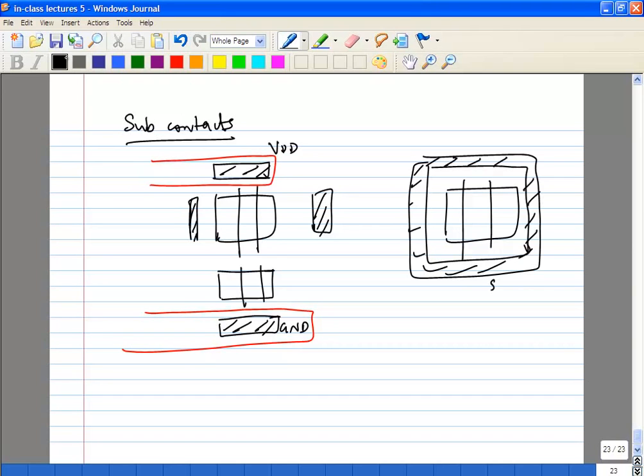So that's as far as your substrate contacts go. So what does the substrate contact do? If you have a switching transistor, say an inverter given a clock signal, the substrate will always have some impedance, some inductance or whatever. So definitely your substrate will be wiggling. What effectively is happening is your noisy transistor is injecting something into the substrate. If other transistors share the same substrate, they will pick up this noise through that substrate.